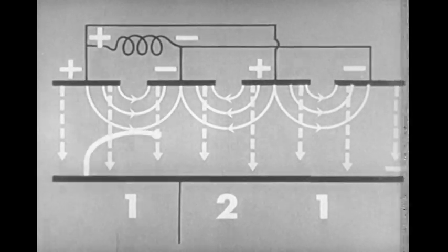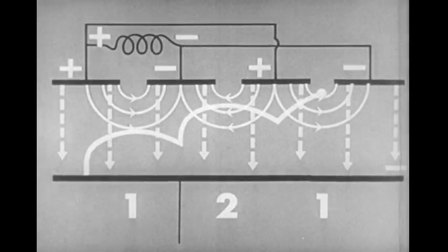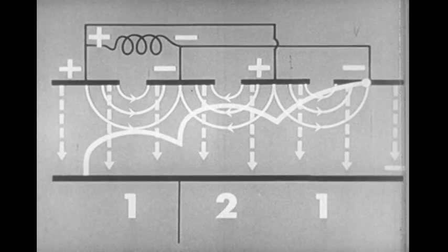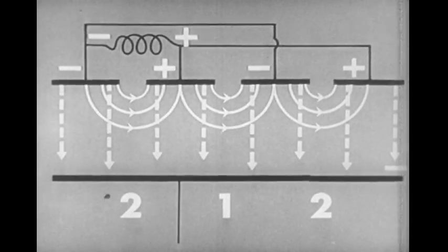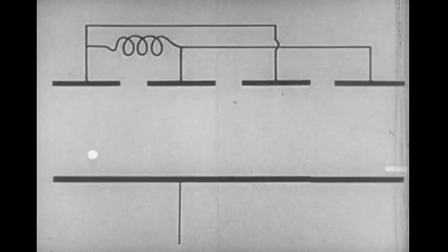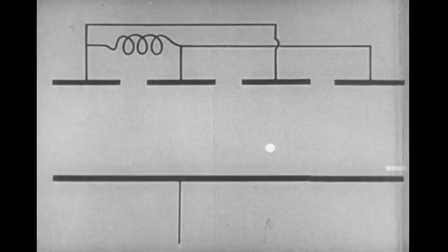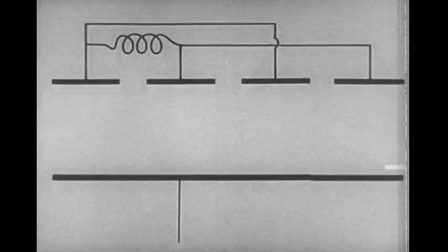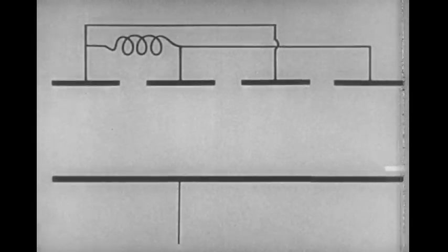All electrons which move from the cathode to the anode will follow this course. Of course, in a pulsed magnetron oscillator, where the electric field does not exist between pulses, the electrons will be affected only by the magnetic field, and so will be returned to the cathode. Now let's look at a typical magnetron.